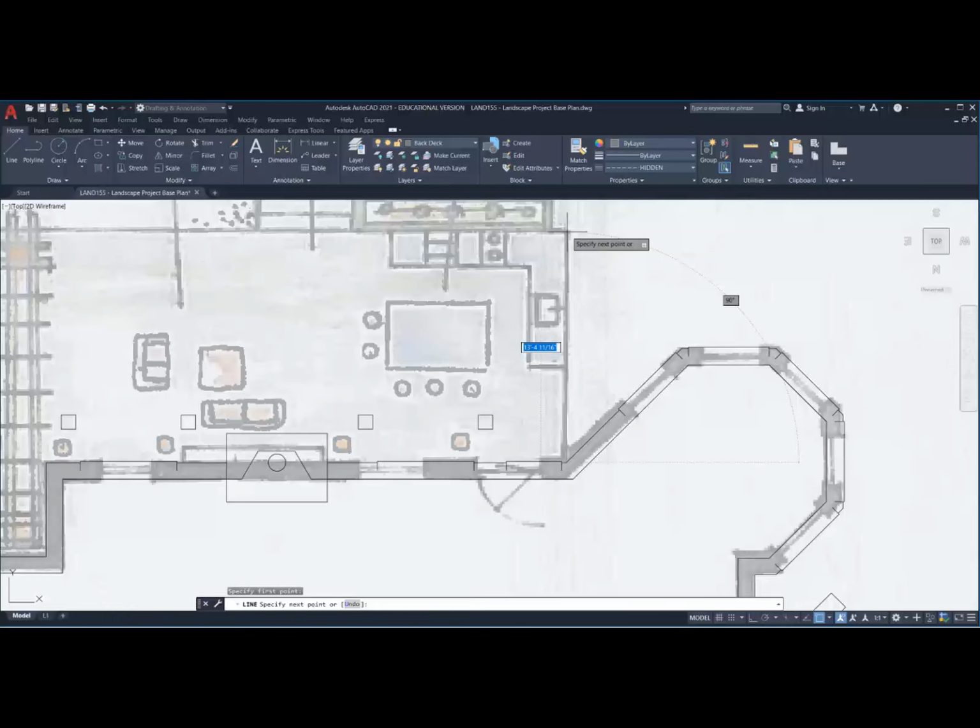I don't want to use fractional inches here. I want the values to be whole values like 13 feet, 0 inches, or any multiple of 3 inch, 4 inch, or 6 inch. So 13 foot 3, 13 foot 4, or 13 foot 6. I can also use a 13 foot 9 or a 13 foot 8. Those are more common in our industry to be used as sizes. So here I'm going to go with 13 foot 6 inches.